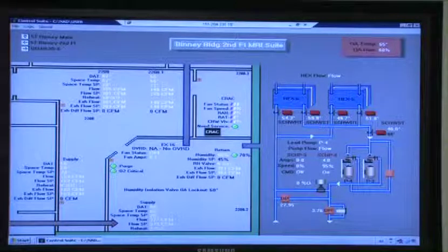There's two valves. It doesn't show the status of the blocking valve on the screen though. The two-position valve status is not shown on here. There's a modulating reheat valve, and then there's a two-position isolation valve. Can someone draw it? I don't understand that.